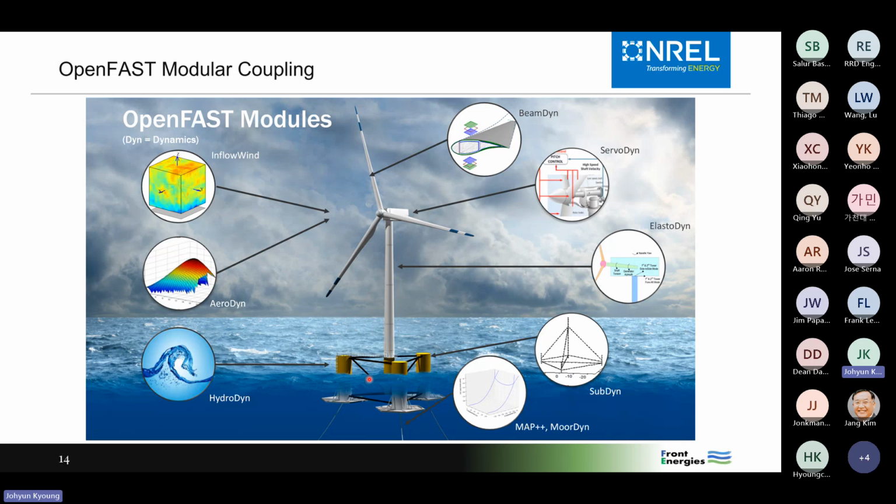But at each section, does your Morrison equation take into account just the motion of the rigid body? No, it takes into account full flexibility. It's sending the motion, the displacement, velocity all along the element. I see. So the velocity of the beam includes the deformation velocity.